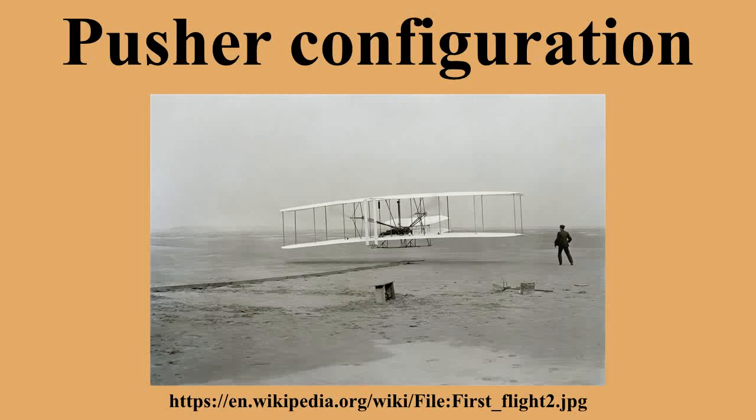Safety. The engine is mounted behind the crew and passenger compartments, so fuel does not have to flow past personnel. Any leak will vent behind the aircraft, and any engine fire will be directed behind the aircraft. Similarly, propeller failure is less likely to directly endanger the crew. Leaks of fuel, oil or coolant from the engine stream away from the aircraft instead of becoming a risk to the pilot, other occupants, and any whole aircraft parachute installation.